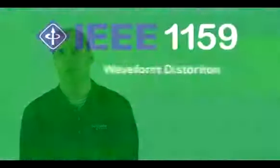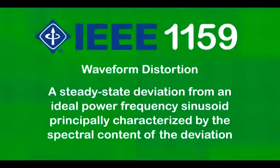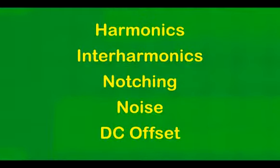Waveform distortion is defined by IEEE 1159-2009 as a steady-state deviation from an ideal power frequency sinusoid, principally characterized by the spectral content of the deviation. IEEE 1159 lists 5 primary types of waveform distortion.